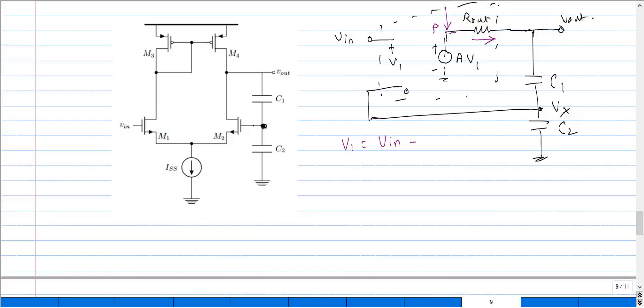Since we have a capacitor, what I would get at the top would be C1 divided by C1 plus C2 times Vout. And this is the potential that I have across V1. If this is multiplied with the gain, then that corresponds to the node potential Vp here. So now let us come back to our business: what would be the current over here?